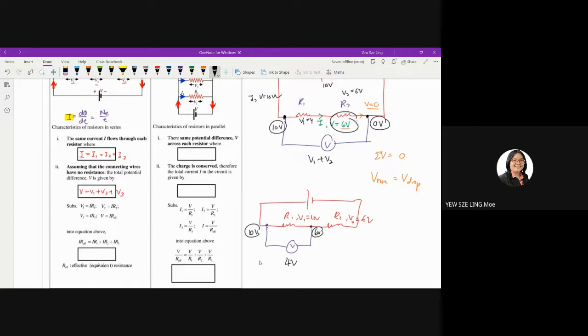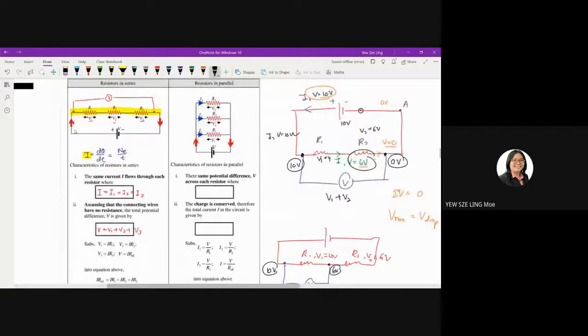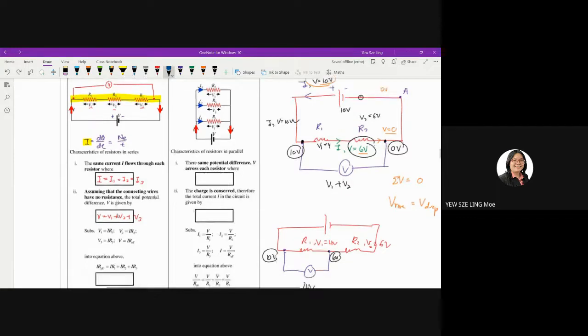If you look at the circuit as a whole, for example, in this case I have the resistors in series, original diagram right here, tengok balik diagram asal. If I put my voltmeter across all 3 resistors, then my V would be equal to V1 plus V2 plus V3. But if I put it from here to here, then my voltmeter would give me a reading V1 plus V2. That's it. So it depends on how you connect it. But if you connect them in series, you just add up the values, total them up.